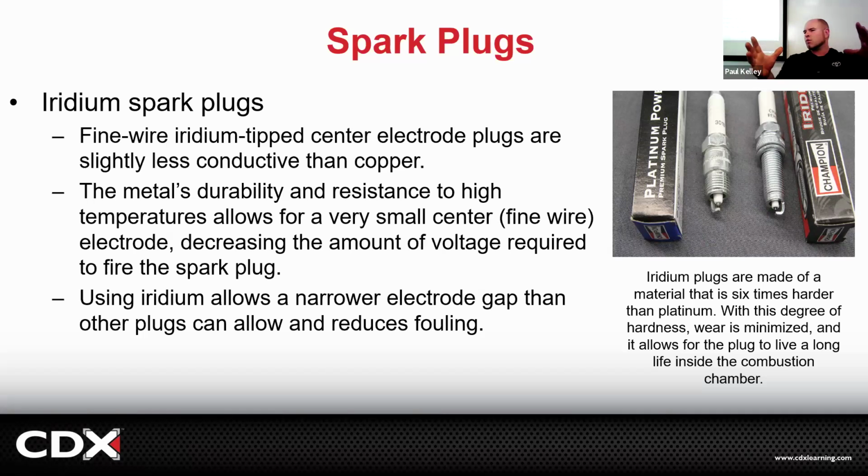But if your coils are lasting over 100,000, you're probably not going to have a coil failure. You're probably not going to have to do the spark plugs until either they're due or until you have a coil failure, which is at high miles. And then you're probably like, hey, we need to do this coil, and your spark plugs are also due based on maintenance. And so it's just not a tune-up. They're not coming in being like, hey, I need my spark plugs done at 24,000. It's more like, hey, it's 120,000. The car's 11, 12, 13 years old, and it's still got the original spark plugs in it.